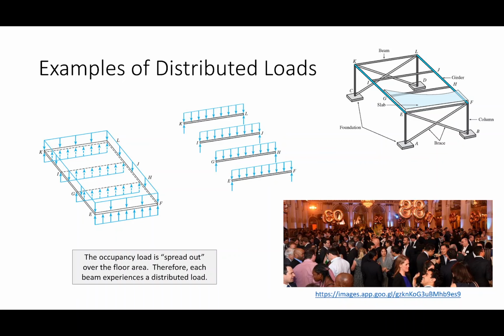Whereas if we were designing a library, we would design a library floor system for something like 150 pounds per square foot. Why the sudden increase in load? Because libraries have to support all the book stacks that contain all the books that college students don't read, right? So, that was a joke, not very funny. No, but in all seriousness, the loads that we design for are a function of what the structure is being used for, what's going to occupy the system, okay? Does that make sense? Everybody okay with that?